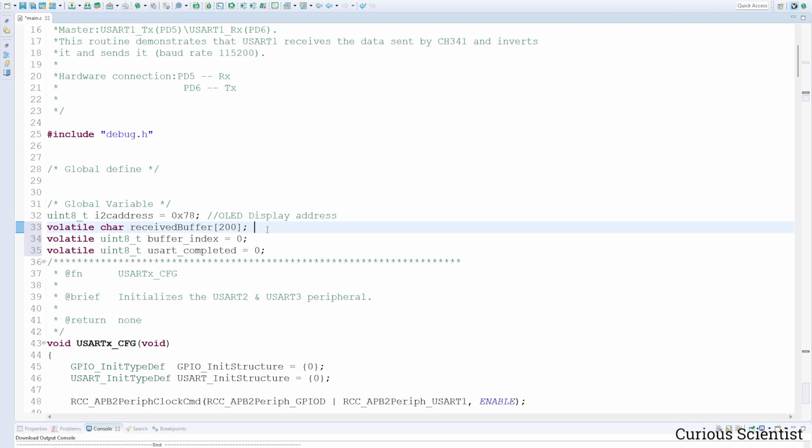So 5 times 12, that is 60. So actually we could print 60 characters, and since it's a USART buffer, we need to have an extra character for the null terminate. So if we are really nitpicking and we are low on memory, then this could be 61 characters, because we store 60 bytes, which is the 60 characters, plus 1 byte in the buffer, which will be the null terminate character. So that's how we could work with this. But I just have a ridiculously large size here.